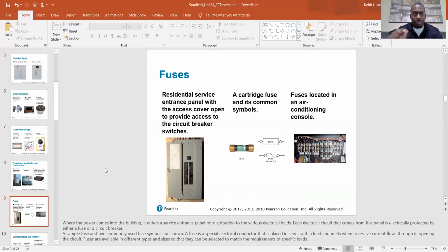Inside that fuse there's a little fusible link that'll melt when it heats up to a certain level, because electricity generates heat, and the more current, the more heat. They're engineered to break at a certain level that indicates an overcurrent. So if the fuse is rated for 20 amps, 21 amps will be hot enough to melt that link on the inside, blow the fuse, and cut the power to the unit to prevent any further damage.